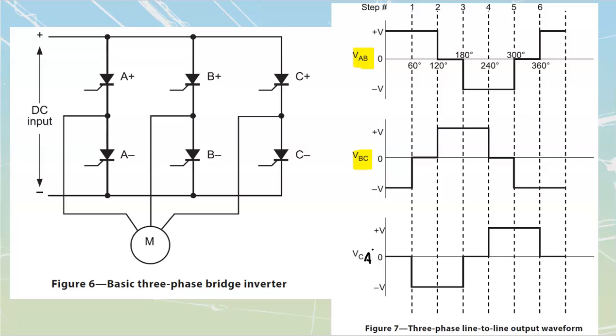Going through this one really quickly, because we're not going to go through every single step, what we do see is that the voltage is always in reference from one to the other. Subscript notation means that I'm standing on the last one. Remember, your shoes are the very last thing that you put on before you go out. Therefore, since shoes are the last thing that you put on, that's where you are going to be standing. That's the analogy that we use to take a look at double subscript notation. So when I'm standing on B looking at A, I'm going to see something. When I'm standing on C looking at B, I'm going to see something. When I'm standing on A looking at C, I'm going to see something as well.